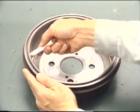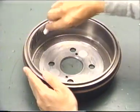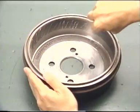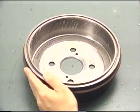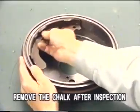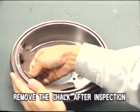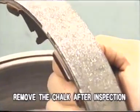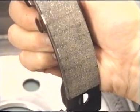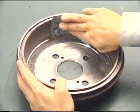Check that the brake lining and drum make contact appropriately by applying chalk on the inside of the drum and placing the brake shoe inside. Remove the chalk after inspection. If not making contact properly, repair the lining using a brake shoe grinder or else replace the shoe.